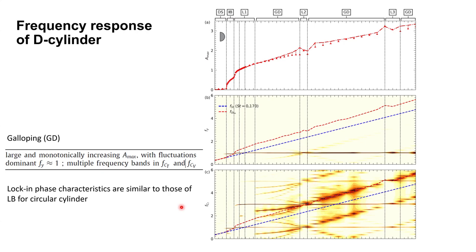And that too we have explained with the modified natural frequency, because somebody can definitely argue about what these frequencies are, as they are not really matching even with the Strouhal frequency or other frequencies. So the explanation is actually that the Strouhal frequency also gets modified in the event of a large motion of the D section cylinder.